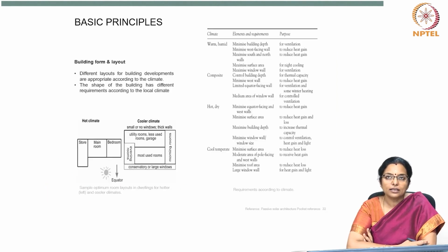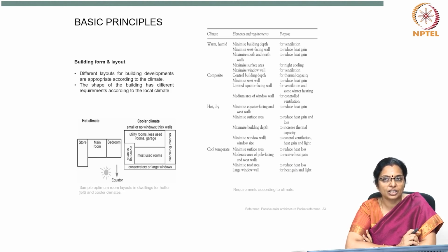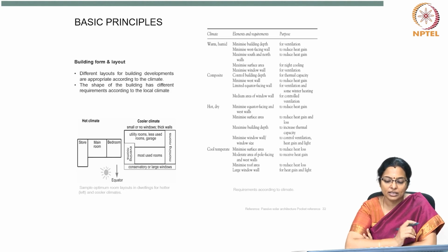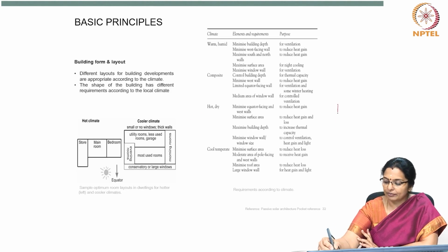Now, let us look at the building layout. As the warm humid climate zones are located near the equator, the orientation of the settlements pattern should be placed preferably on the southern or northern slopes. The best orientation is longer side facing north and south direction to protect from the solar radiation.